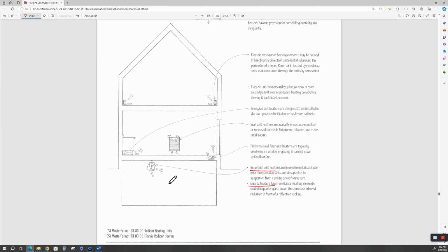What you have to do is balance your BTUs and your airflow. Again, you may need 2 of these in a space. Who knows? But each one of these needs to be on its own circuit, its own home run. And a home run is nothing but a line from the panel box to the appliance.